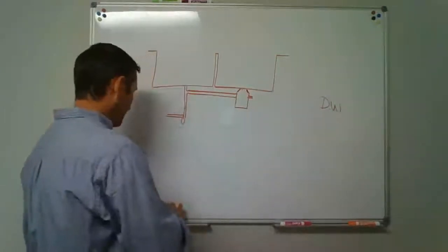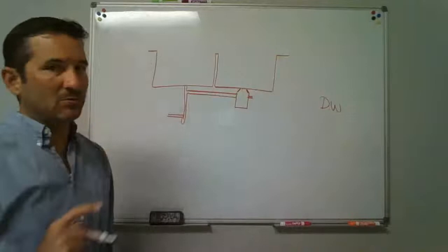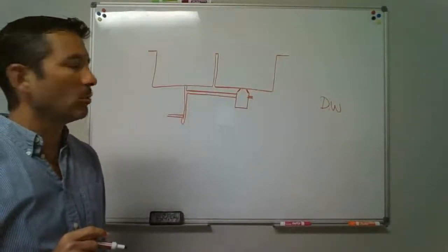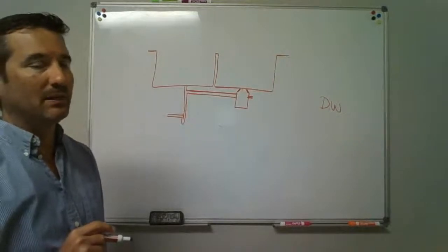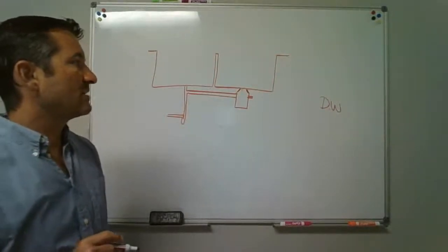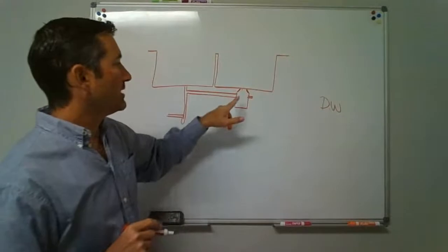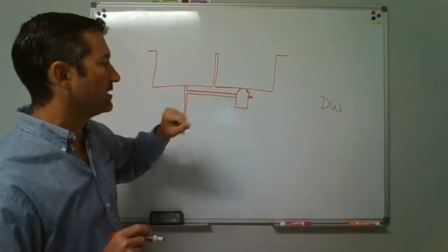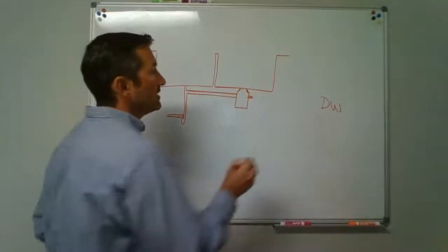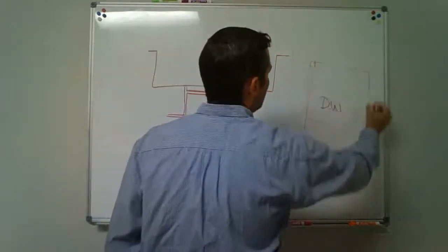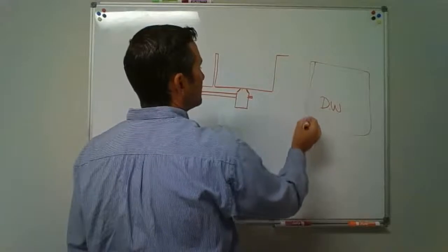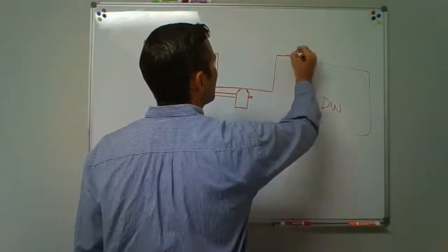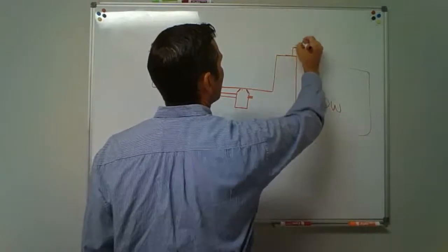Now, you may see one of these. They're getting fewer and far between, just because it would be an older style kitchen that somebody hasn't updated yet. But it says that when you're connecting to a dishwasher Y connection like we had before, or a garbage disposal that's under the kitchen sink, your dishwasher drain line is going to go to one of the places that they said, which is a deck mounted vacuum breaker.